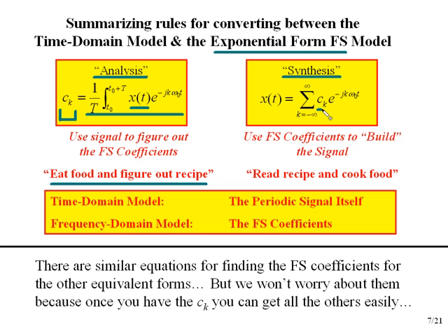It says you give me the Fourier series coefficients, all infinite of them, and I can sum this series up, at least in theory, and approximately in practice. I could go from minus 100,000 up to plus 100,000 if I wish. And so I'm using the Fourier series coefficients to build or synthesize the signal. I've been given the frequency domain model and I'm creating the time domain model.